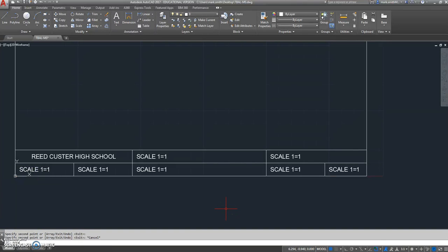Then I'm going to go dtext, I'm going to click on, hit escape, DDEDIT, sorry. Type DDEDIT, click on this, and I'm going to type DATE, not DD, DATE, colon, and then the date.